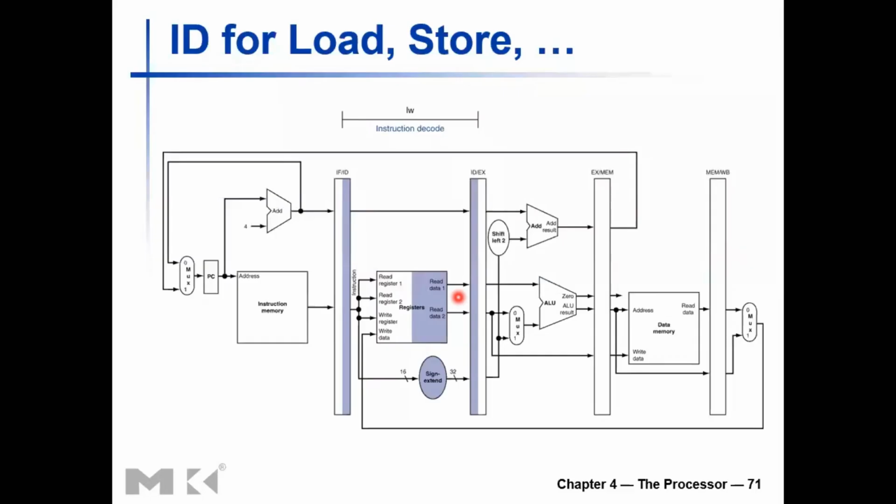Yes, so what is available at these lines, right? We have two 32-bit lines here. What are available there at that moment at the start of the clock cycle are the data values corresponding to the previous instruction, which is currently in the ALU stage, right?